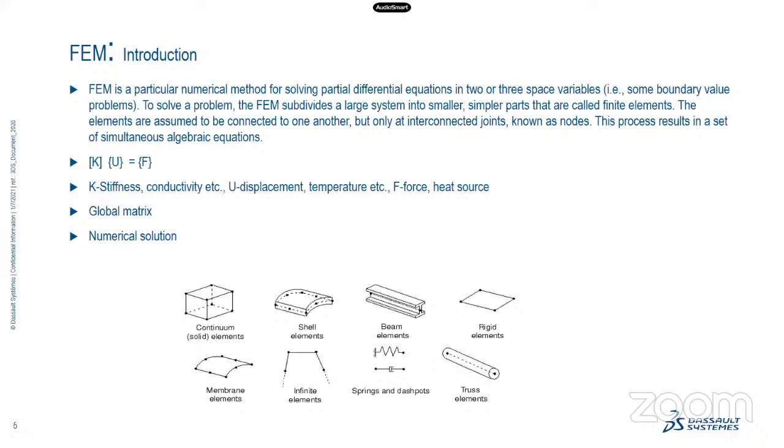Another variant of the FEM is the spectral finite element method. It is a similar method, but we solve it in the frequency domain. But the concept of elements and then globally arranging them is the same. We can model structures using different elements like continuum elements with 3 degrees of freedom, 3D shell elements, and beam elements.